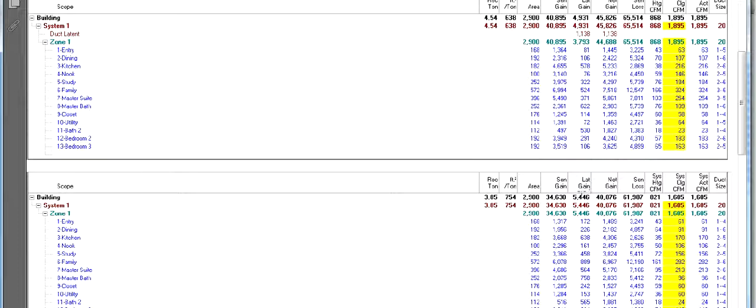In our older house, where we did nothing to stop the air infiltration, 5,446 BTU of humidity is entering the house. So the 2009 house is a little bit more efficient in that, but the numbers are so small I would not worry about it. Again, only the Manual J could give us all this information.